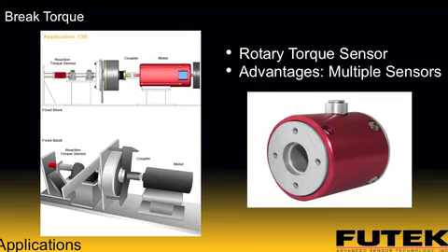For our last example here, I'm going to show you guys how a torque sensor is paired with a USB kit. This customer was interested in measuring the input versus output torque in their system. The Sensit software could then measure both torques and subtract to show the difference. Now, if we were to consider the same approach for a dynamometer-like setup, where the load cell was used with the moment arm to measure the torque, knowing the length of the moment arm, the software could be used to measure and calculate the units to torque.